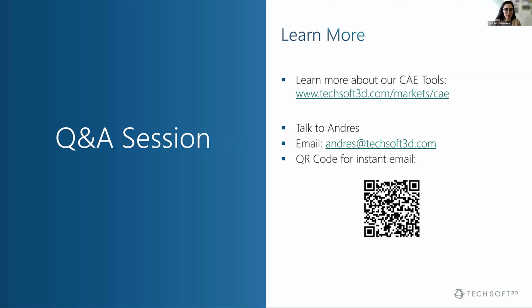Oh, I think I missed this one. Does CEETRON Mesh only accept tessellation data as input, or are there any capabilities of surface or volume mesh adaptation? Thanks. First answer is yes, it's only tessellations, and although it has some built-in repair capabilities like filling up holes and removing very small edges, we tend to recommend using a valid mesh as input for the surface remeshing, actually. In terms of adaptation, well, there's mesh size control that can be connected to any way of computing.